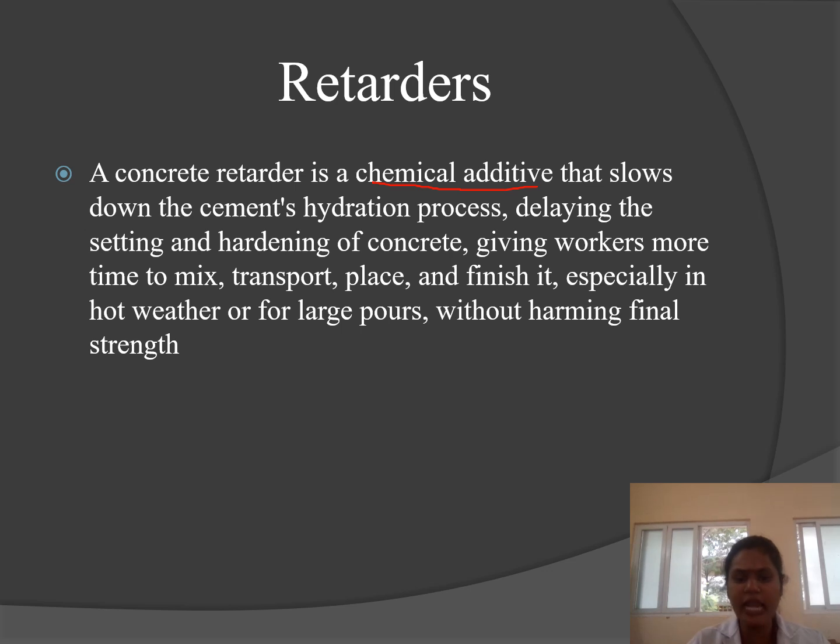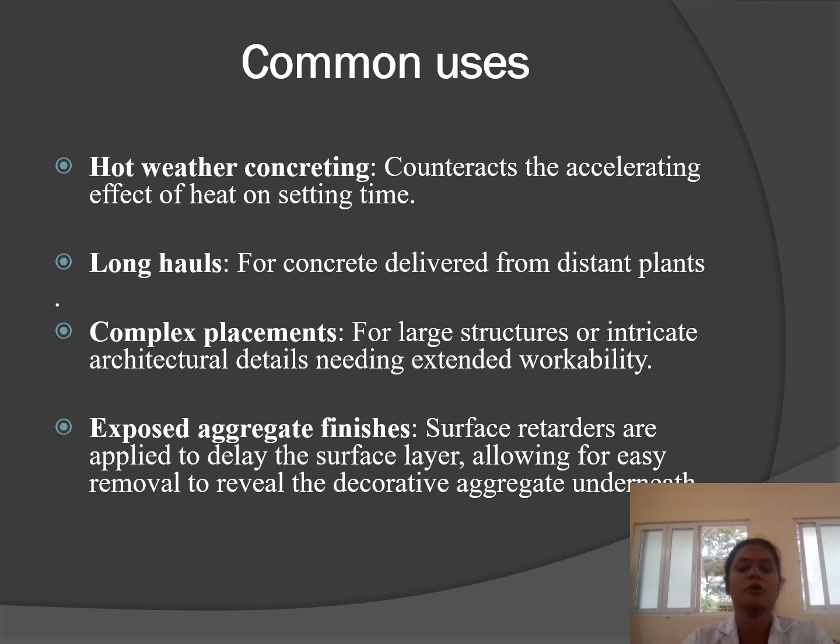without harming final strength. Common uses for retarders: hot weather concrete, to counteract the accelerating effect of heat on setting time. Long hauls, for concrete delivered to distant placement sites. Complex placement for large pours or intricate architectural details, leading to extended workability.